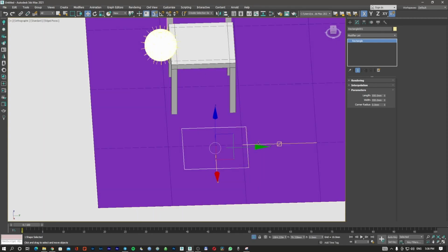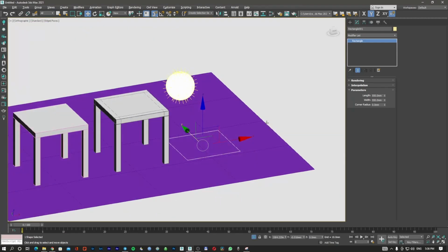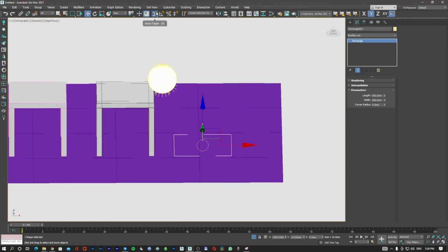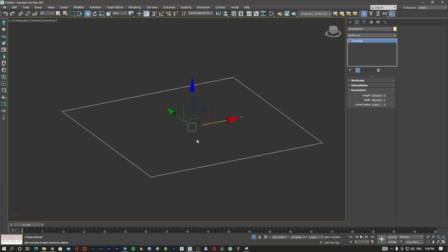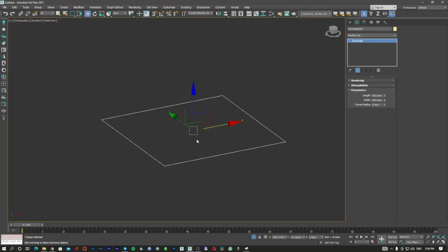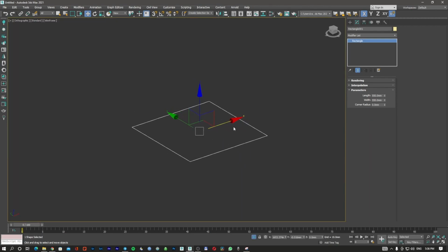So what I'm going to do next, I'm gonna move it here in the middle to have all of them in the same line so we can see all of them. I'm gonna isolate this with Alt Q. With F3 I'm gonna go to the dark view so I can understand better what's happening. And right now I know that my object is on 0, 0.